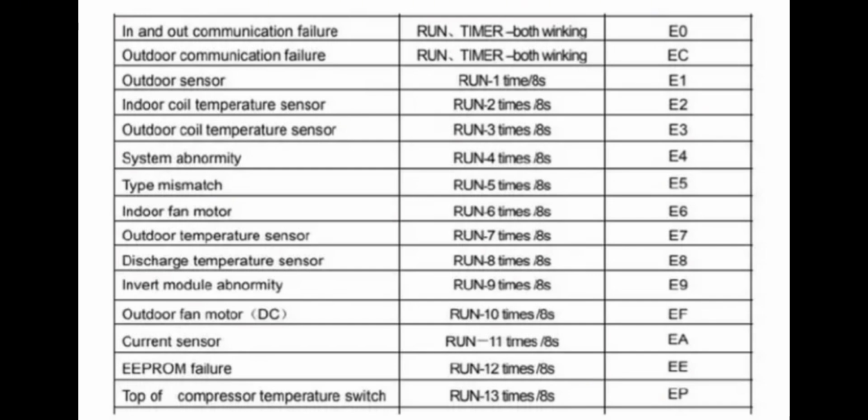E1 is outdoor sensor. Sometimes it's the indoor room temperature sensor. It's a sensor problem. Check the connection in between the indoor temperature sensor. You can replace the sensor or you can replace the main PCB.